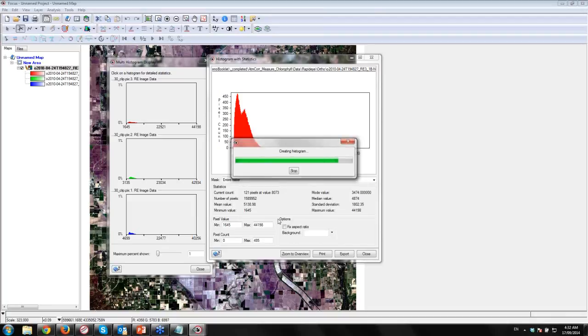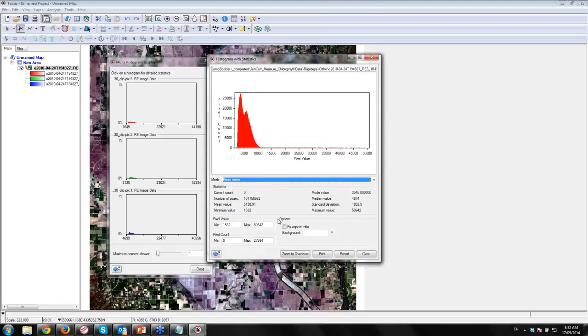So the atmospheric correction, not only will it remove the effects of the atmosphere, but it will also give us everything on a fixed, relative scale from 0 to 100, so that we can compare the numeric values from field to field.